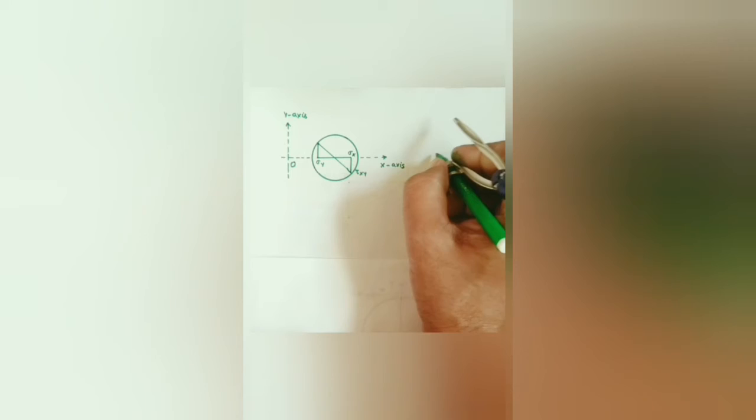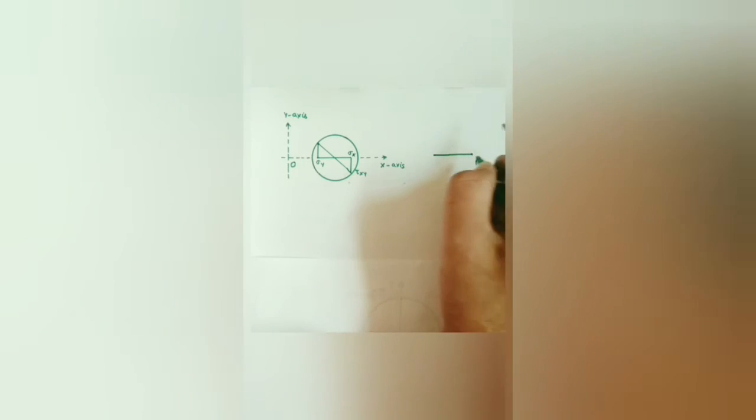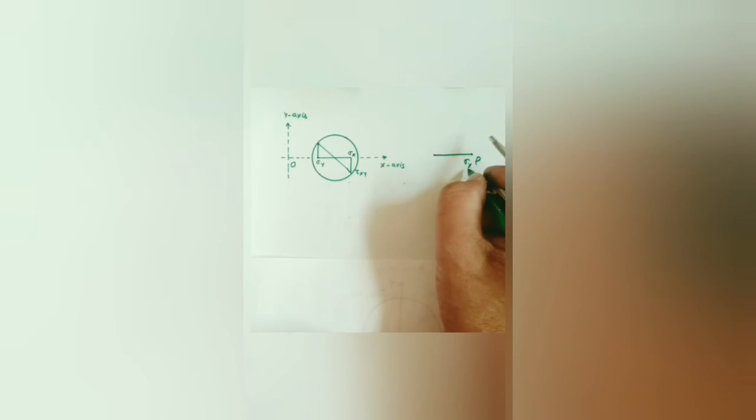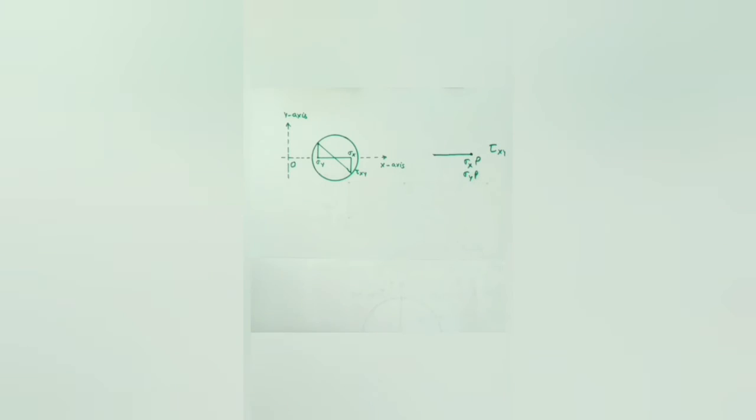In this particular case, since sigma x is p and sigma y is also p, these 2 points coincide. Since tau xy is also 0, there is no vertical line here, so the Mohr circle is just a point.